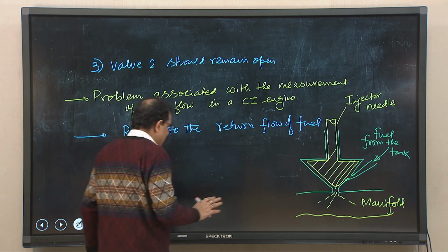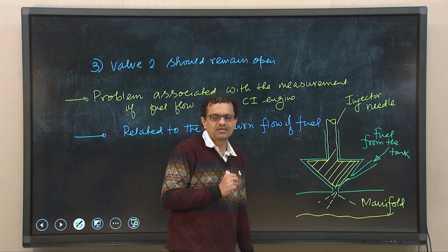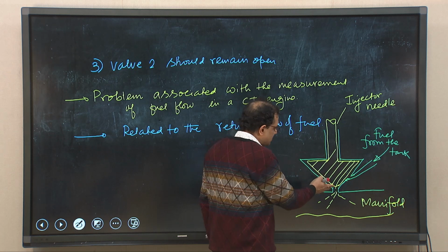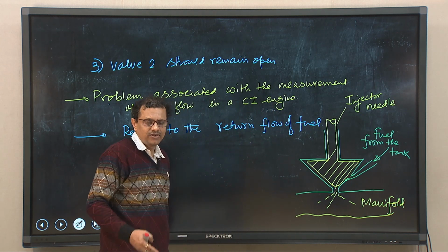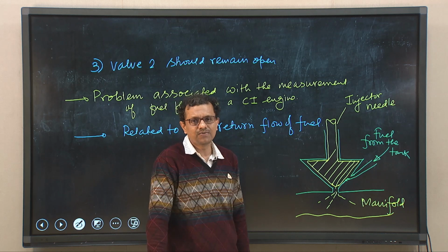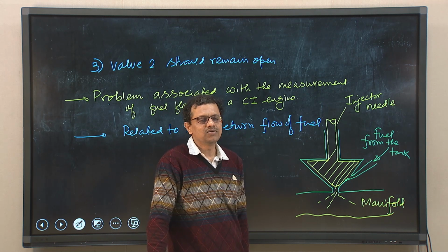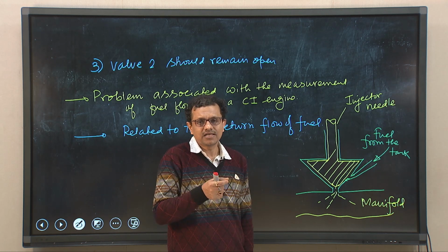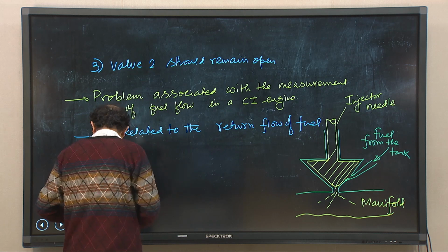And another problem I should tell you, while measuring this fuel flow rate using this technique, as I said, these surfaces are at relatively higher temperature. So, liquid fuel might get evaporated, and that vapor block can also create problematic issues in measuring the fuel flow rate. Okay.